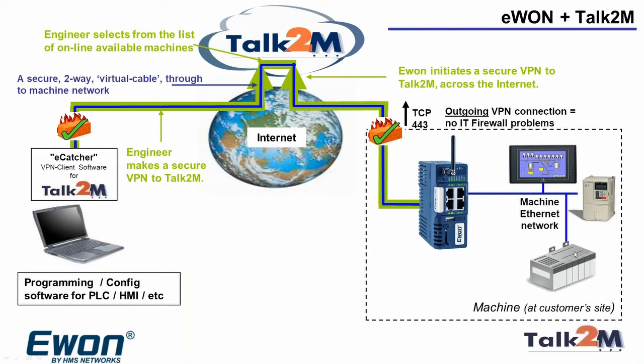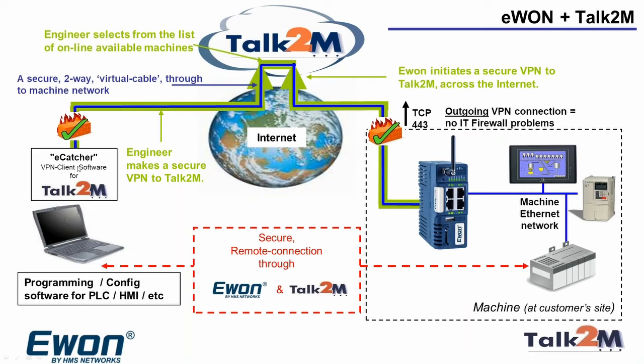So as I said before, the golden rule here is if you can put this laptop over here on these blue cables with your head inside the panel when you're on site, you can do exactly the same things over here when your laptop and the site are many miles apart. Once you've got this connection up and running and you can ping that Ewon, you can ping that HMI, you can ping that PLC, you can ping that drive, you can then launch the programming software for those devices and program them as if you were on site on the end of a direct cable.